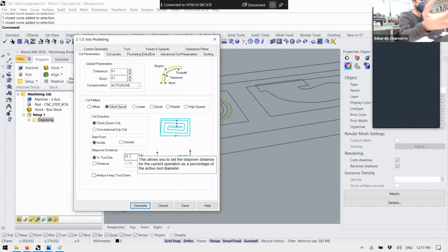Tool diameter. This is the offset. On the side, on the X and Y, you are making a pocket. You remember that I said that we are playing at 4,500 to 5,000 RPM speed. I went a little bit higher. So instead of putting 40, that will be a standard movement on the side, I will reduce to 35. I prefer to go a little bit faster, but less movement on the side. It's a little balance. You can always play with this.